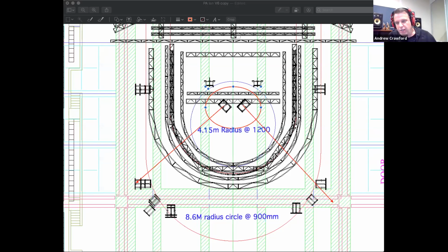While you're talking, Juzzy, I want to know, do you do steering on those subs, or are they all just one big block? No, all one big block, all one big coherent source is what I do. Basically, when you introduce steering, you sacrifice SPL. Yeah, there is that. And also, typically the line lengths we see of those are probably not long enough to have any advantage of steering.